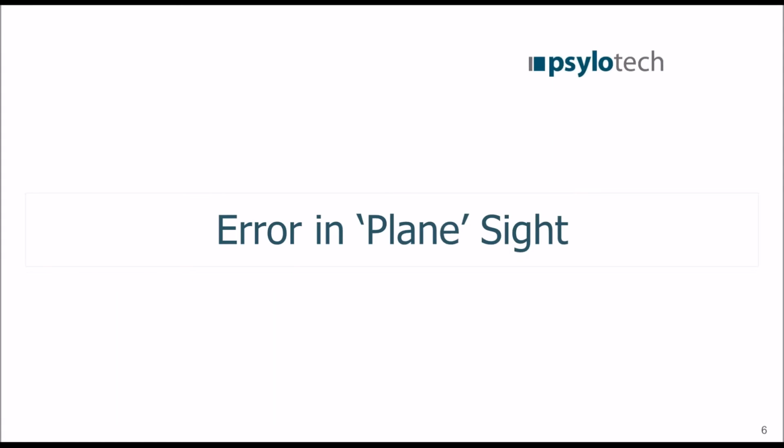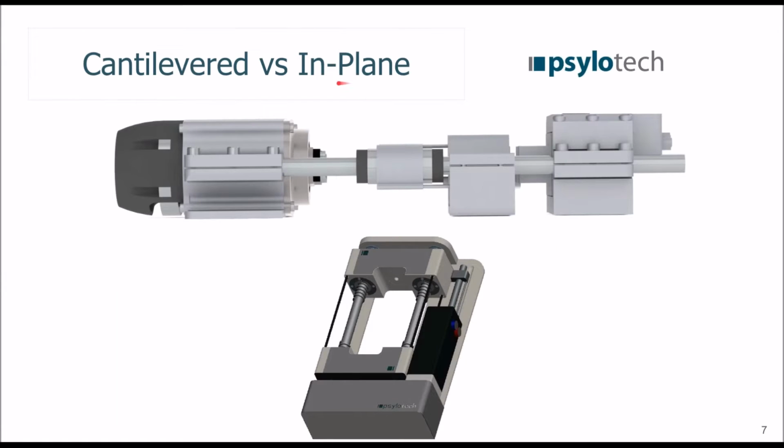Coming into the first key benefit of the load frame in performing these experiments was what happens with high magnification DIC. You can see right here, let me get my pen out, the objective comes in here from the top, and you can imagine this images the specimen, which would be placed right here, or sorry, more in the center here. Now if this specimen moves out of plane, it can cause issues, especially with these high resolution 2D optics we have.